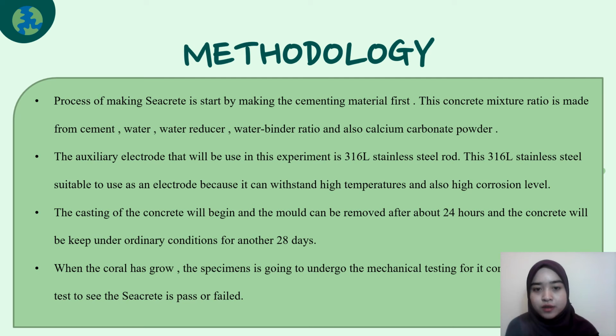The casting for the concrete will begin and the mold will be removed after about 24 hours, and the concrete will be kept under ordinary conditions for another 28 days. The ordinary condition is like the experiment setup, which we will submerge it in the seawater and will undergo the electrodeposition method for another 28 days to see if the coral grows or not. When the coral has grown, the specimen is going to undergo the mechanical testing for me to see whether the SEACRETE passed or failed.